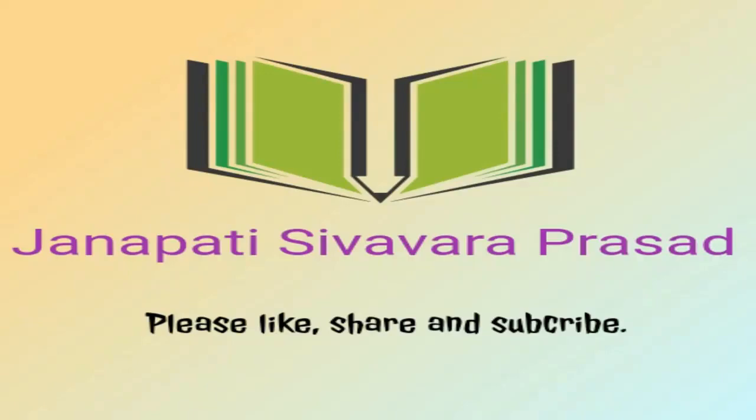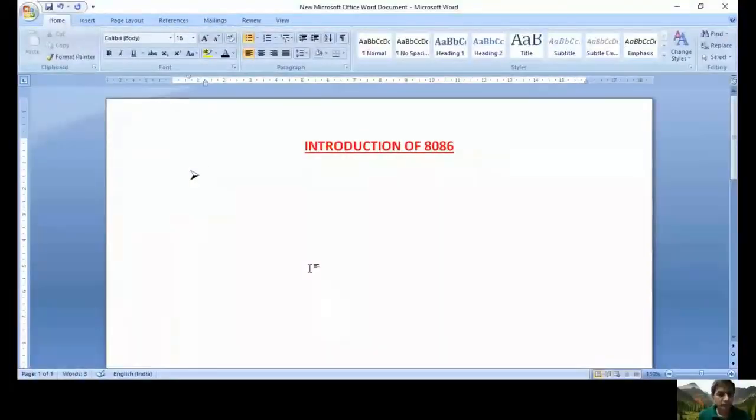Hi friends, this video covers the introduction of 8086. Let us see, the 8086 is a 16-bit processor. So it contains 16 data lines, generally from D0 to D15. Because of 16 data lines, the 8086 can take any data from 0000H to FFFFH.